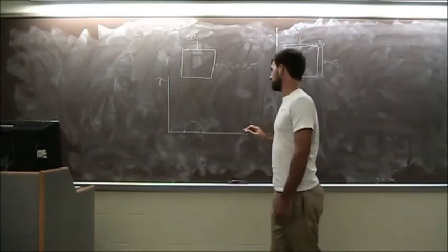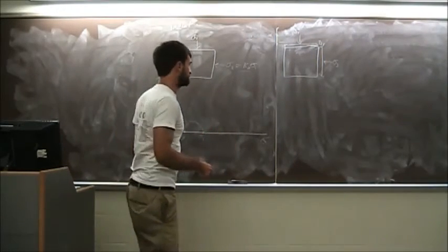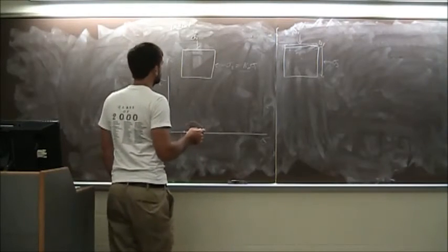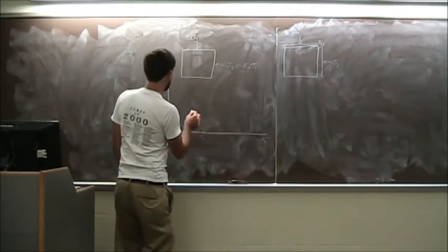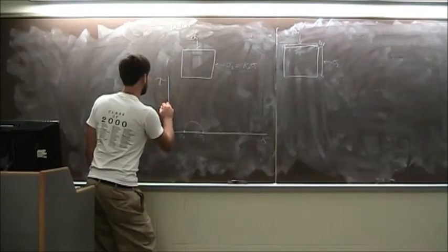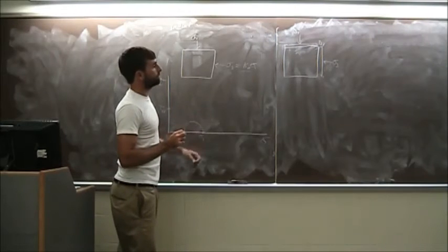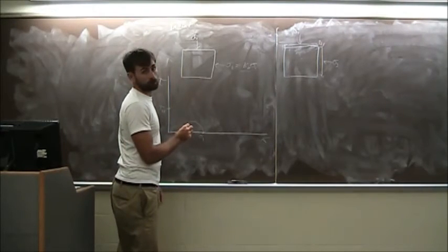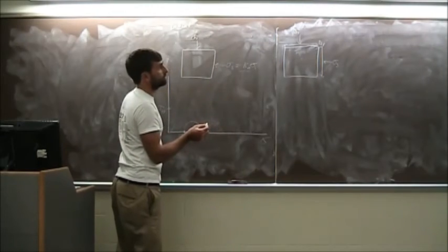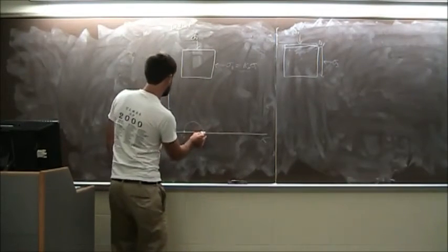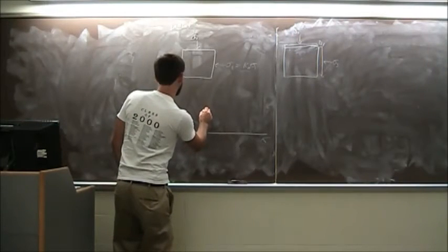So let's look at how the principal planes change during the test. So we know, let's call this tau FF. Let's just say it failed here. So we know one point on our failure circle, and that's sigma 1, tau FF, because tau FF occurs at this stress level. So that's what this point is.